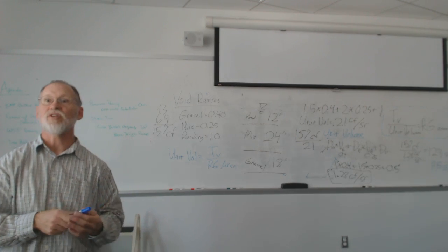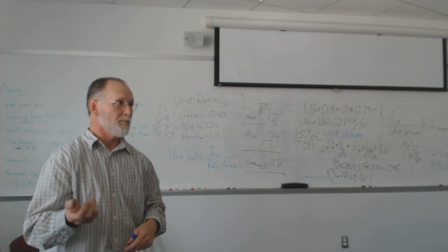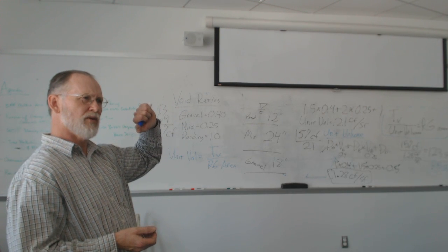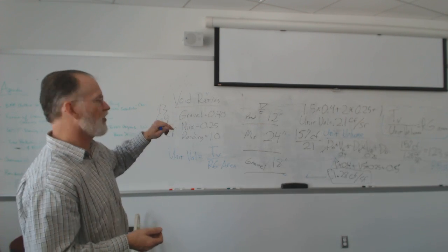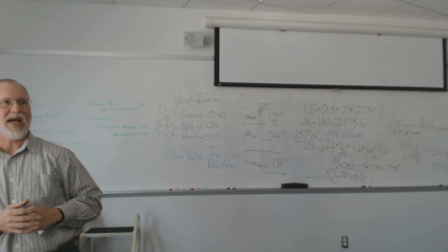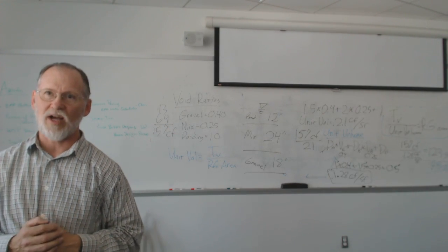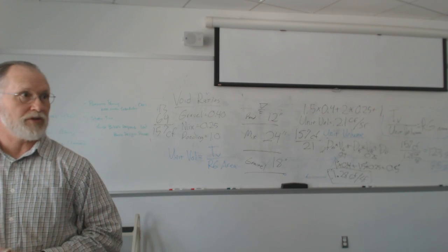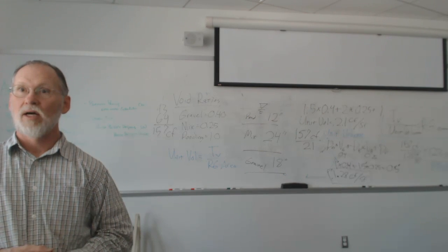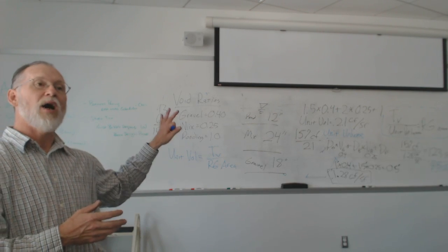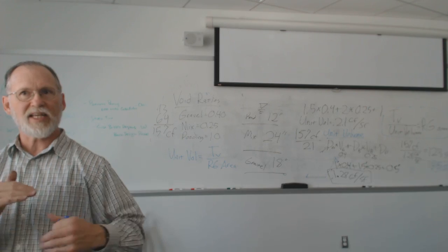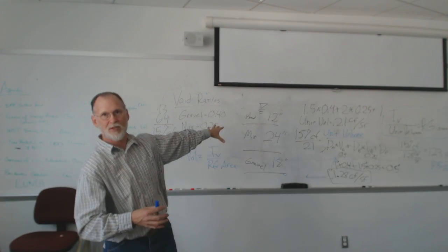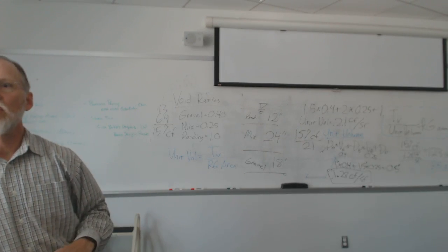In many cases, as you can see from the difference in the design storms, Maryland has a design storm of, is it 2.6? 2.6, so that's over 2.5 times bigger than Virginia's design storm. We're not that far away, but it's a change in how the municipality wants to look at the sizing. So you can definitely make it bigger. I would not go below the 1 inch, because if you're going to all this work of digging the hole and buying the biomix and building this thing, you want to have an impact.